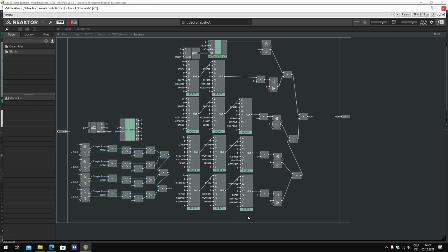The thing with these elliptic filters, at least when you implement them with the direct form 2 that I did, is that when you design them, they are always designed for a specific sample rate in mind. So when I have a sampling rate of 48 kilohertz, I will have different parameters to get a cutoff point at 16 kilohertz. When I have a sampling rate of 96 kilohertz, those will be different. And to make sure that on any sampling rate I have the cutoff and the frequency warping at around the same, I need several different filters.